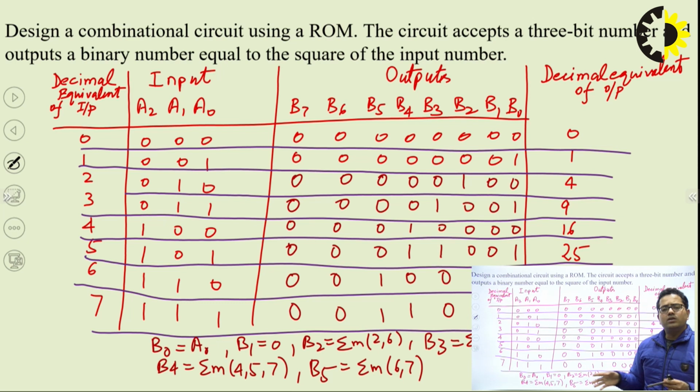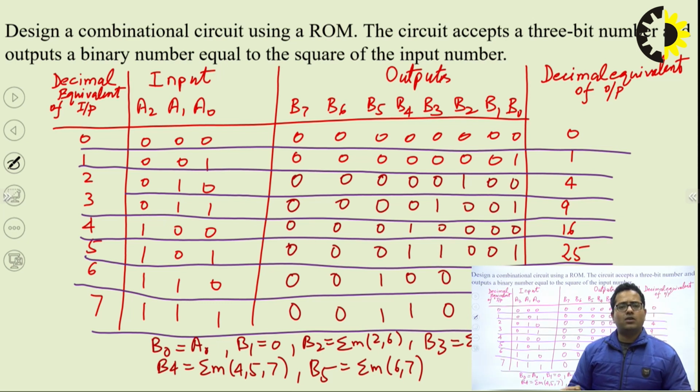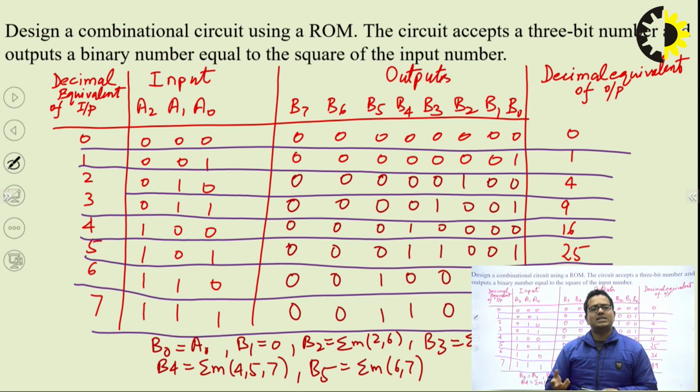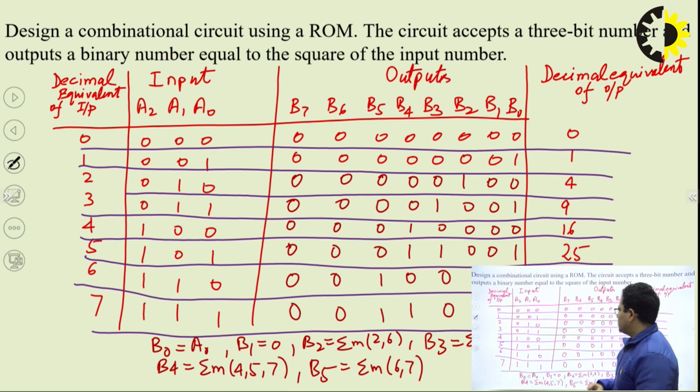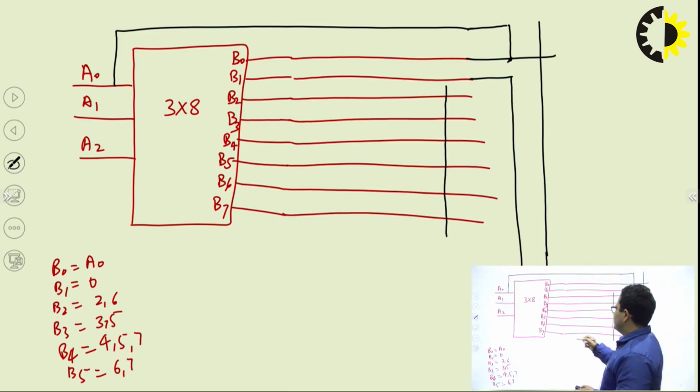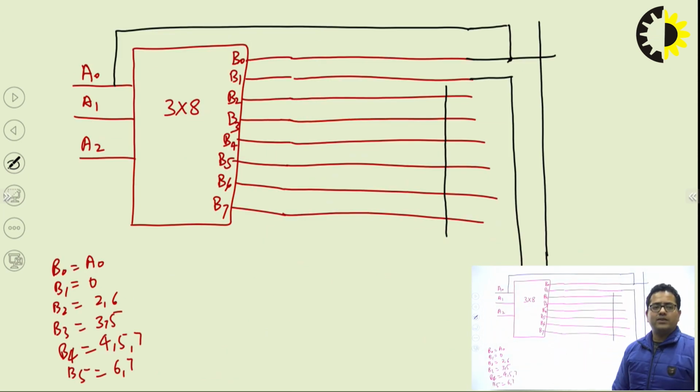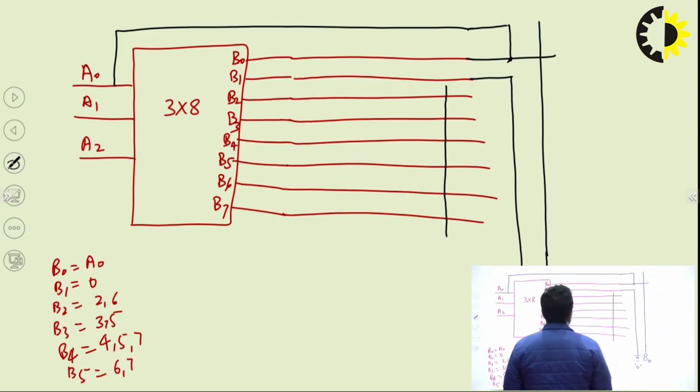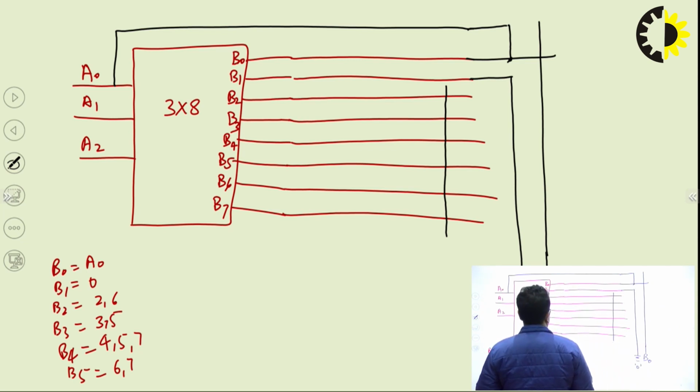So there is no need of taking an OR gate and giving all its inputs as 0. What is the purpose of that? Instead of that, just remove it. So we can remove B6 and B7, right? Although if you have included them, it's not going to matter, it just increases the cost.